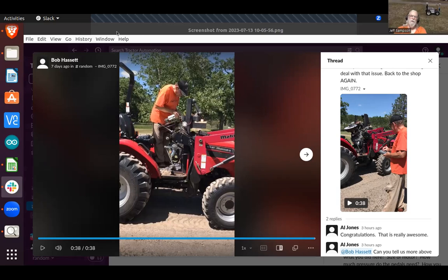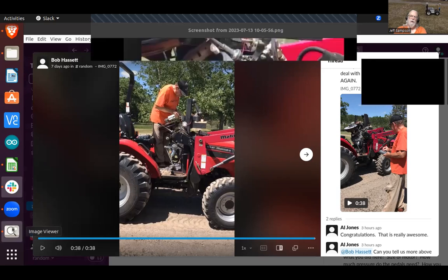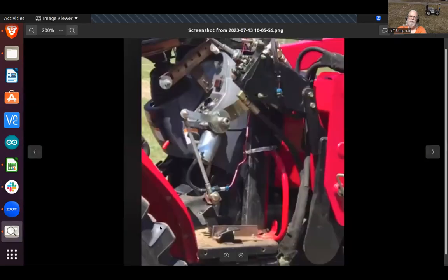The quickest thing you can do on that, controlling your hydrostatic pedal. Yeah, keep that picture up right there. On your motor, you've got that arm coming off the motor and it looks like about a 6-inch arm sticking out. Well, just drill a hole very close to the pivot point, and that will change it a lot. That'll slow it down a lot if you do that. So just drill a hole closer to the center, and you've got lots of room there.